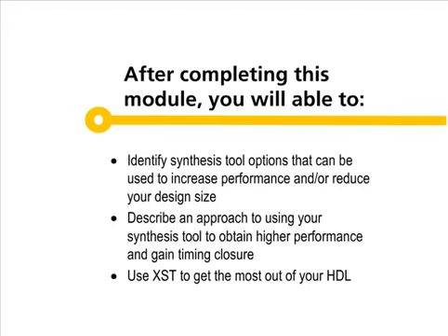After completing this module, you should be able to identify synthesis tool options that can be used to increase performance and/or reduce your design size. You should also be able to describe an approach to using your synthesis tool to obtain higher performance and gain timing closure. And you should be able to find these options as part of the XST software so you can get the most out of your HDL.